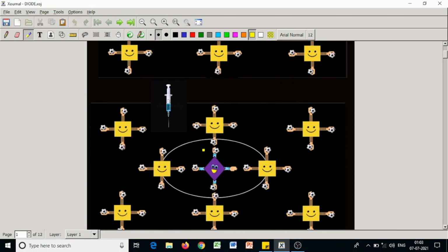When a trivalent element, having 3 valence electrons, say aluminium, is doped, that is, injected into silicon, the 3 outermost electrons of aluminium make covalent bonds with 3 silicon atoms.